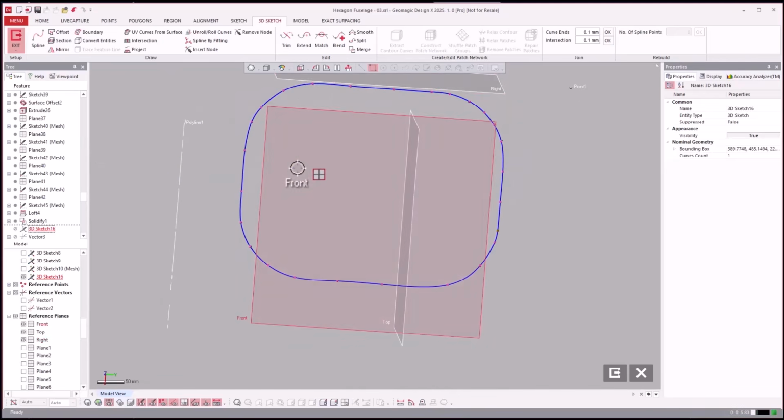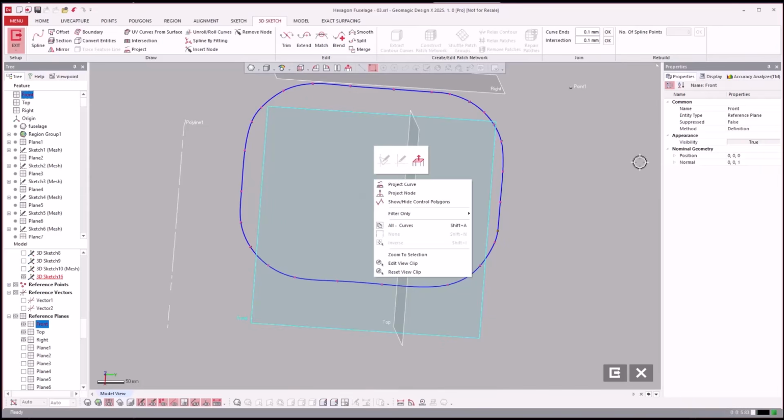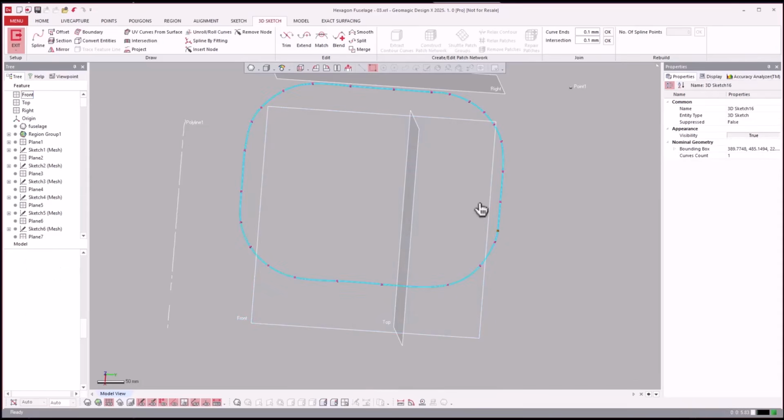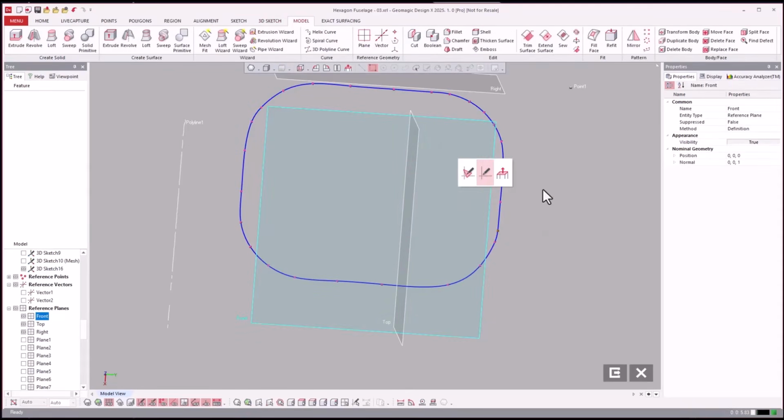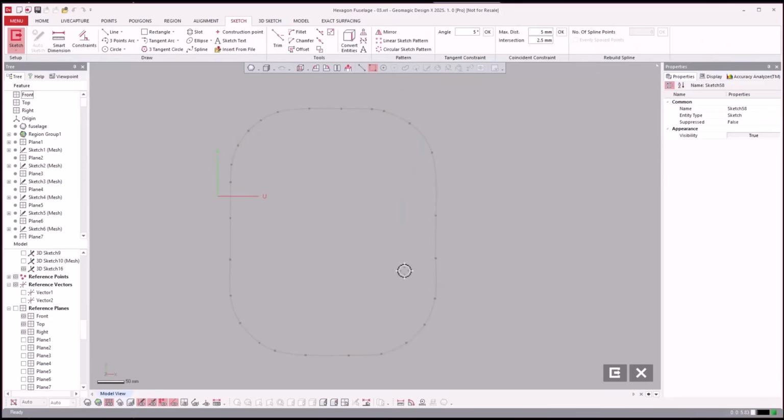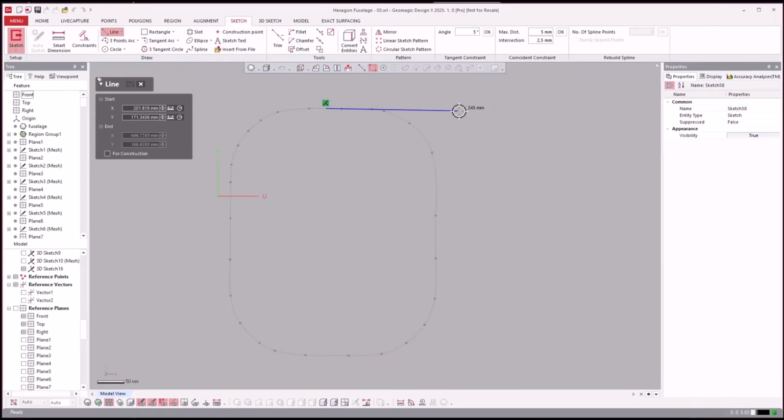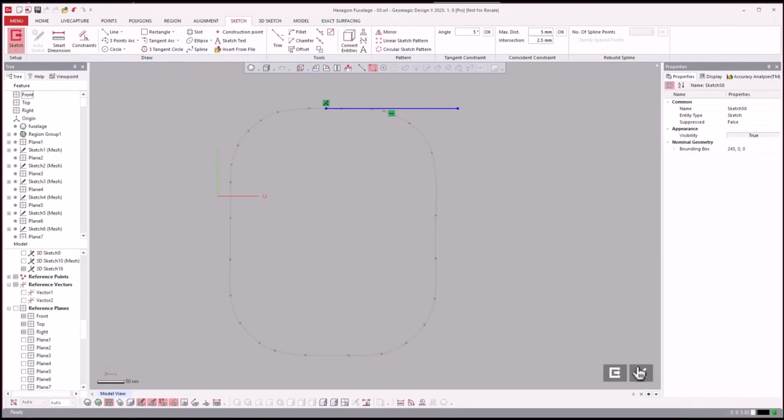And then what I did is you just grab this plane, you get out of that sketch, grab this plane, you could just do a regular sketch, and there's a bunch of things you could do. You could just do a convert entities if you really wanted to, select all this and convert entities, or you can just redraw it like you would if you were doing a mesh sketch, and come in and just draw this, add fillets, and go from there.